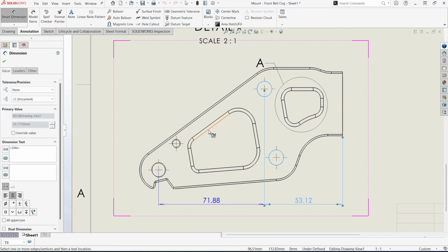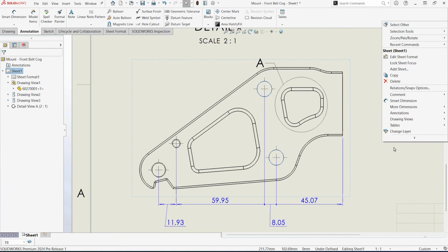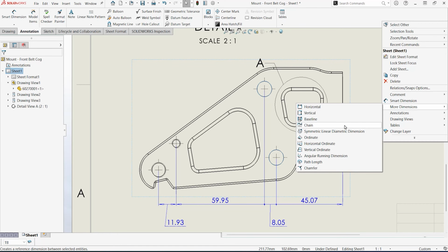These dimensions now come in aligned collinear, reducing otherwise manual cleanup steps. In tight spots, where there may be overlap, a new system option automatically offsets dimension text.